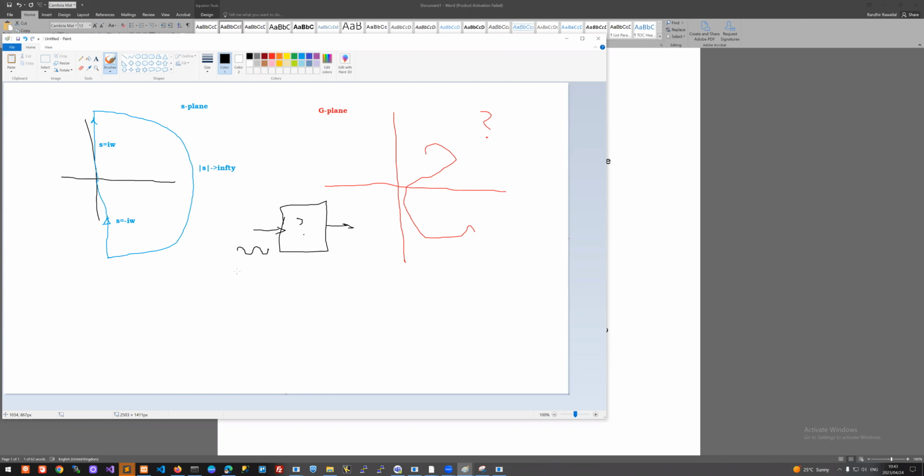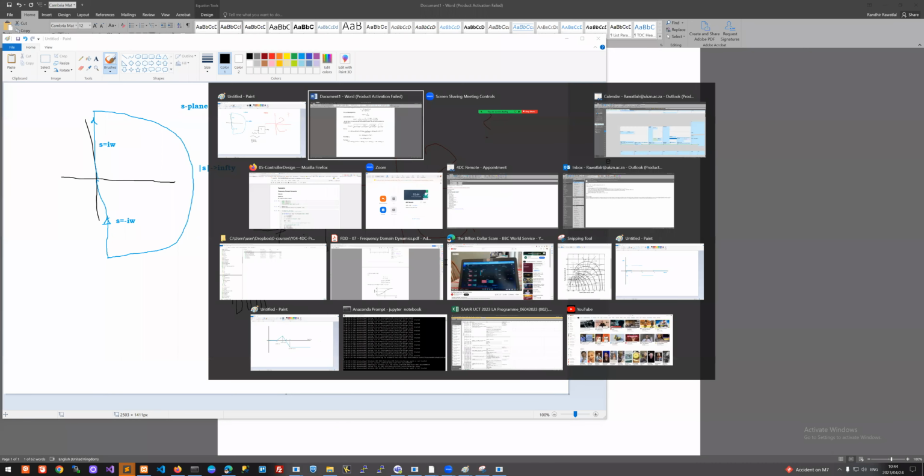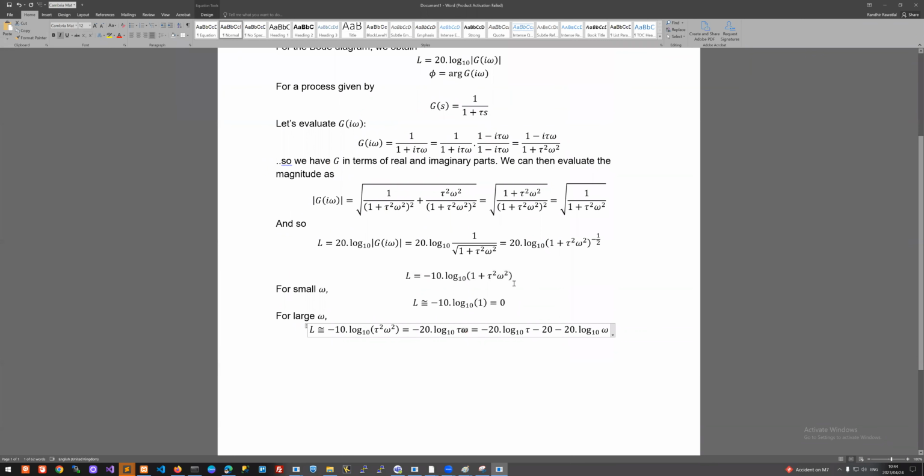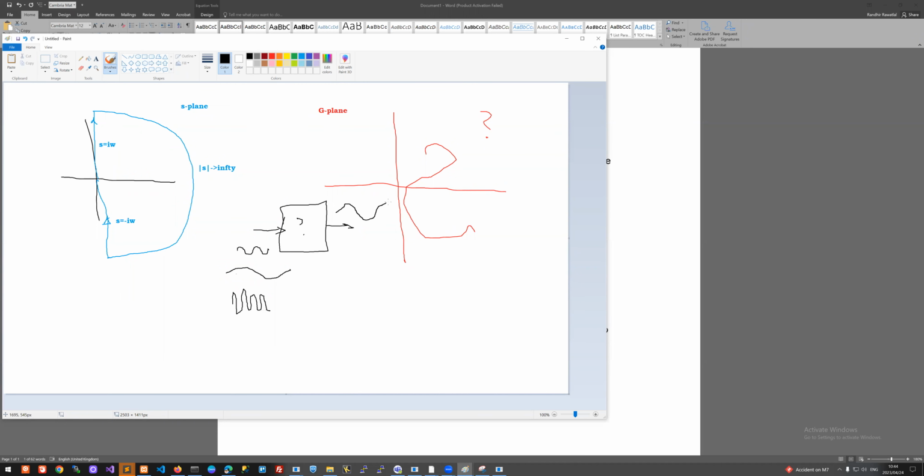And we can apply another sine wave, which maybe has a longer period or a lower frequency, or we could apply another high frequency one and make it do this instead. So we are able to change omega. So we are changing omega, and we are observing how the magnitude changes. And as we said many times now, we get that magnitude by observing y, and we look at the amplitude of y here, and we look at the amplitude of u here.